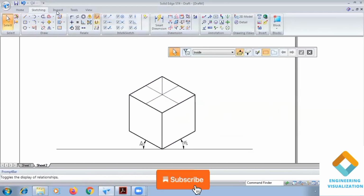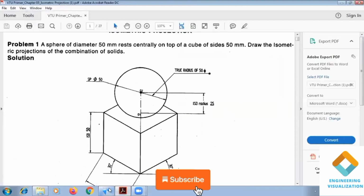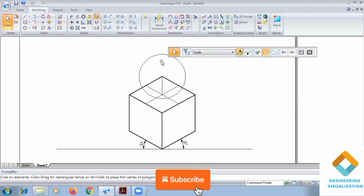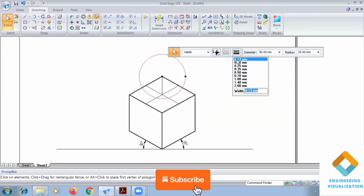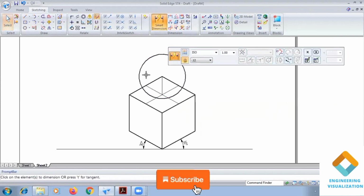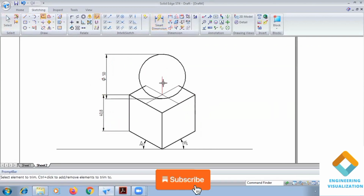Now go to circle and draw here, that is the center of the sphere. Now go to circle and draw a circle of diameter 50. Enter. So that completes the sphere. Always remember, the sphere will be drawn with the actual scale, other solids will be converted into iso. You can check the dimensions here. The sphere is 50, actual dimension, but if you check the dimension of the cube, it is less than 50, because after converting to iso it has smaller dimensions.